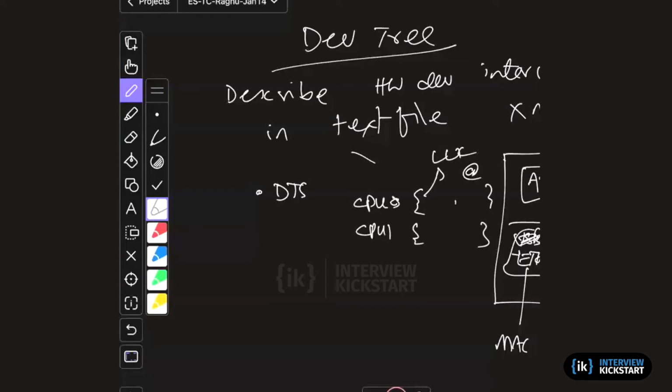So similarly, you will have one entry for I2C, one entry for ETH, or one per device on the platform, right? So this basically describes that particular device, what is the clock, in this case of CPU. For other things, it may have other information.